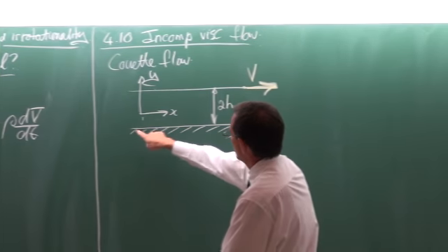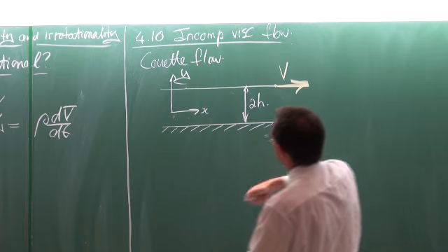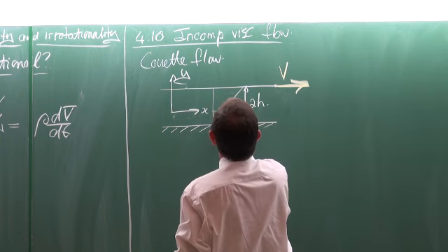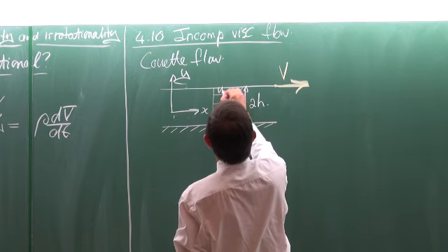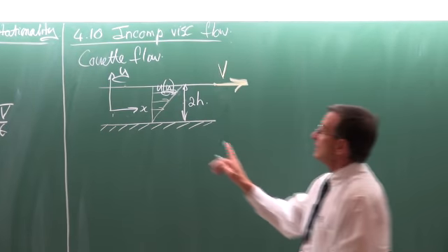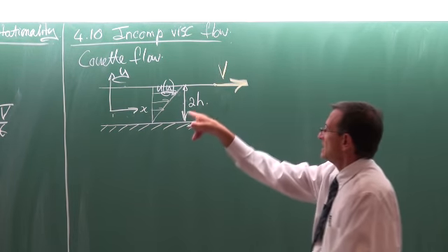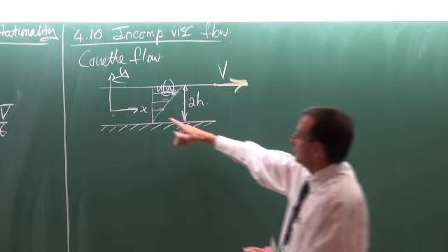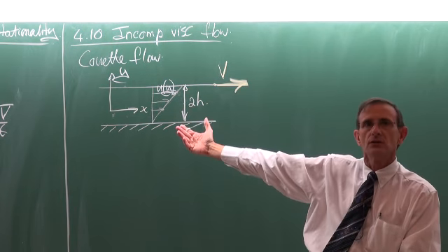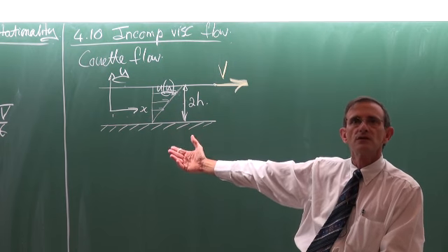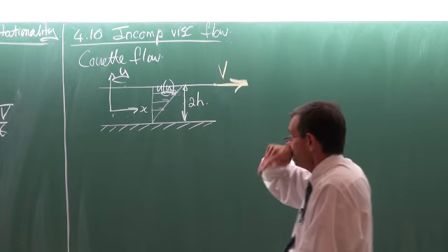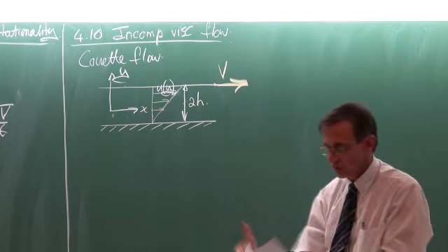So you consider the case where we've got a flat plate like this, another one there, and this one is moved, and the result would now be a velocity distribution on the inside, typically looking like that. The u velocity in the x direction, v in the y, and the z velocity in this direction. So that is typically the velocity distribution. I've drawn it linearly because I know that is going to be the result. But if you just look at it and do experiments and think about it, that is the only logical velocity distribution that this thing can have. But let's see if we can prove it from the differential equations.